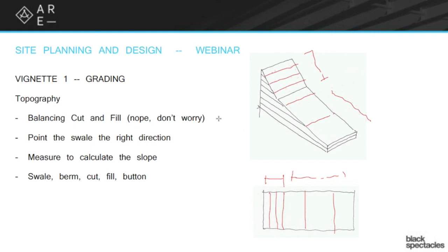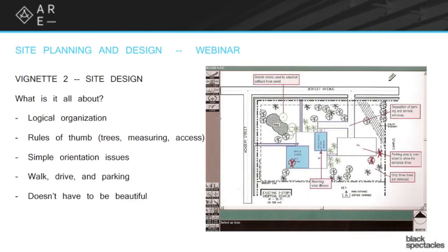So you're always working with the issue at hand, working with the way the water is trying to flow on the site, and just trying to get it to not do the damaging things and go around. Don't be worried about being dramatic. Those pointy swales are okay. The biggest worry you have to have is that there are limitations on what the slopes can be, and you can't let the contours get too close to each other or too far apart from each other. Then you'll be with the wrong slope, like we said.